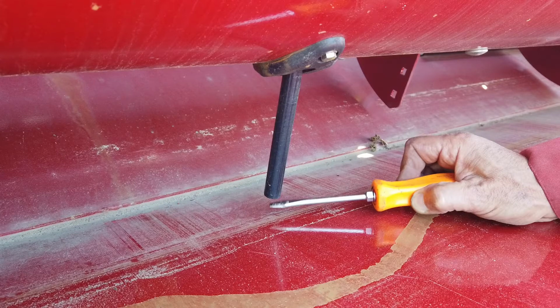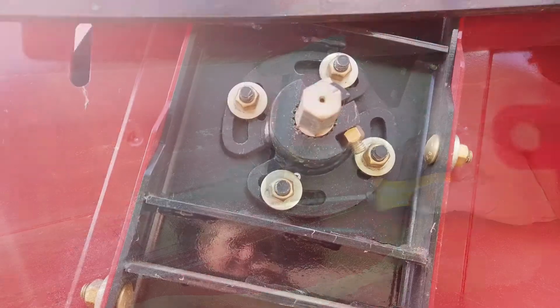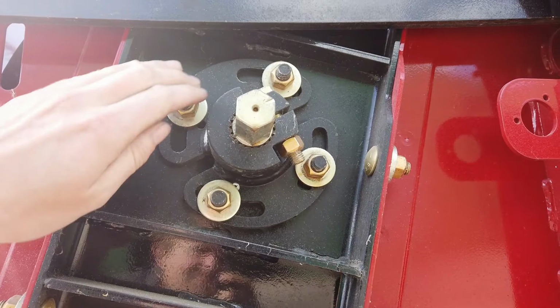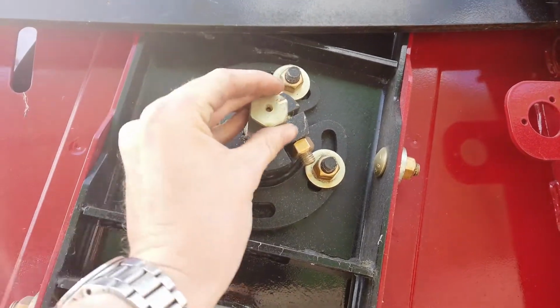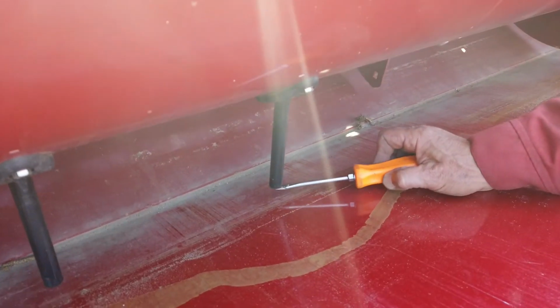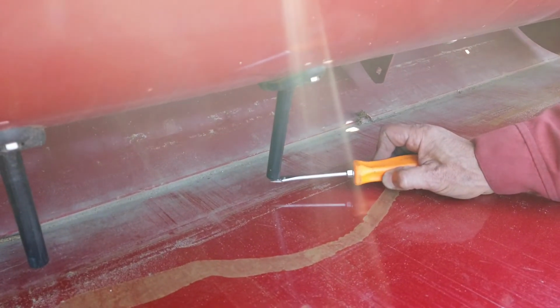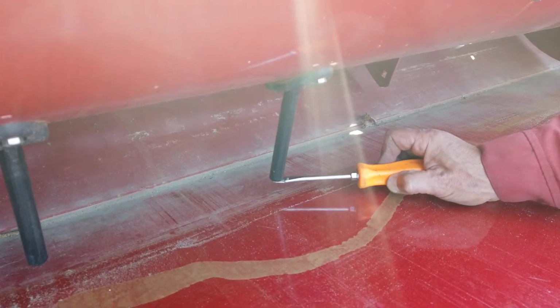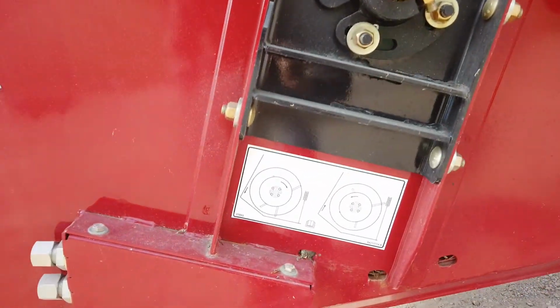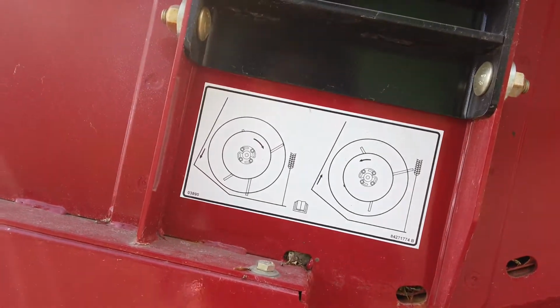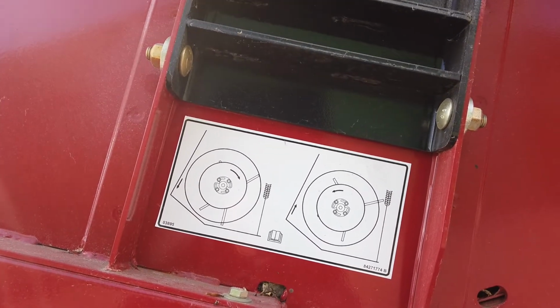This only needs to be done on the right side of the header. Loosen the bolts and using a lever spanner, turn the centre bolt so that the tine clearance is approximately 2 mm less than the flight clearance. However, if wrapping is apparent on the tines, then shorten the tines below the flights. On the 12.1 metre header, the process is exactly the same, excepting a jacking screw is used instead of the centre bolt.